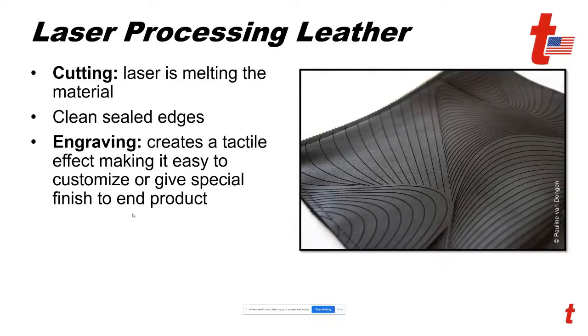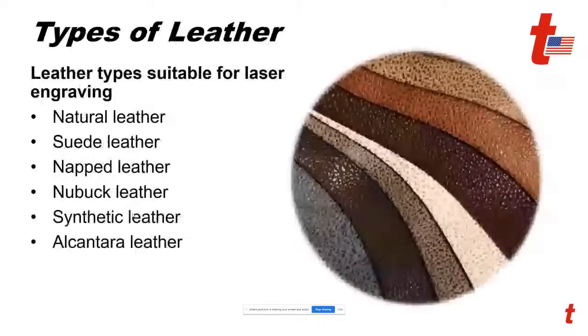Contrast is always going to be darker. So when you engrave into the surface of the leather, I don't care if it's white leather, black, or your tan colors or reds, it's always going to engrave darker into the leather, unless it's a synthetic that is designed to do otherwise, like your leatherette, which actually has a layer inside, but it's synthetic. So understand that in most cases, unless it's designed otherwise, leathers will engrave darker.